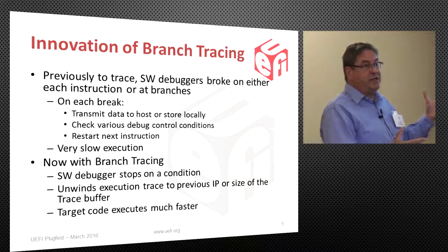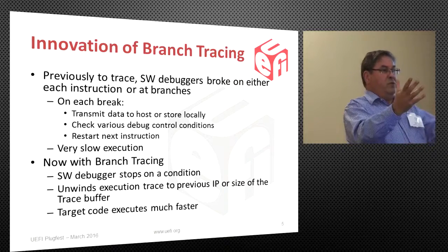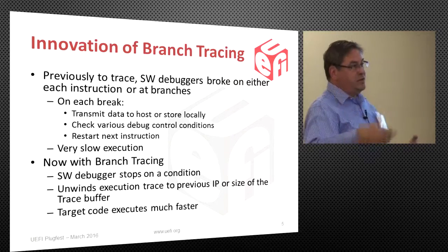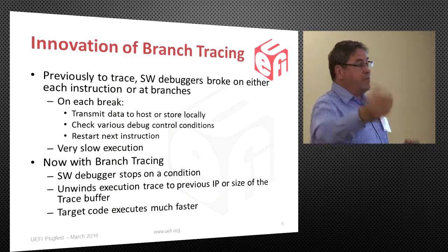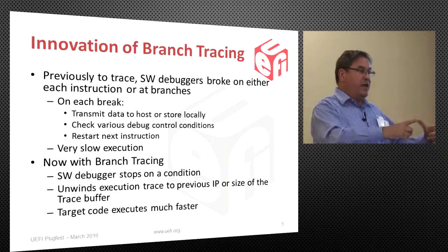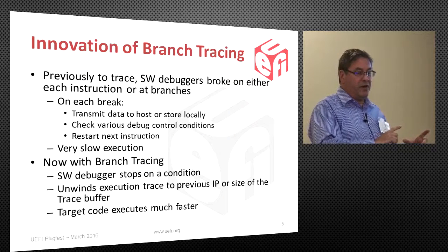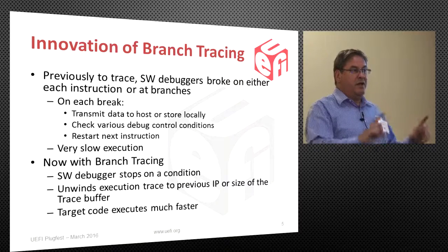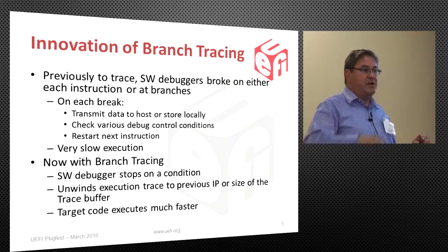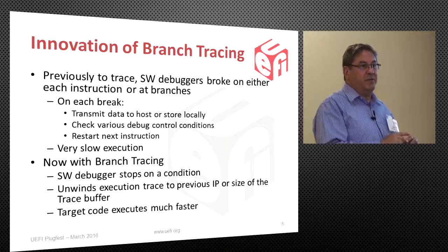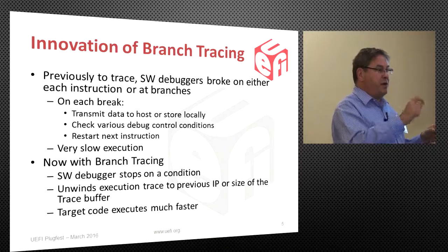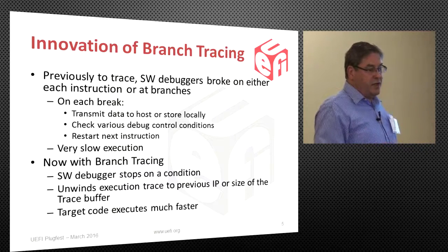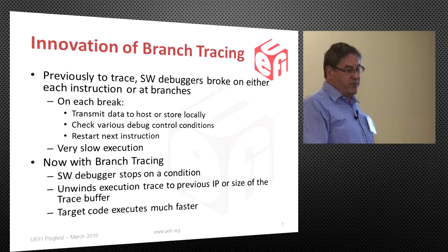So with branch tracing, we've got this buffer. It can be anywhere from 4K to 24K to like 4 megabytes long. And in that buffer are the trace records that are happening. These are very similar to the trace records that the American Arium or the ITPs were using in the past. They were snooping it off of the front side bus, whereas we're actually just having the processors collect it and put it into some memory for us.